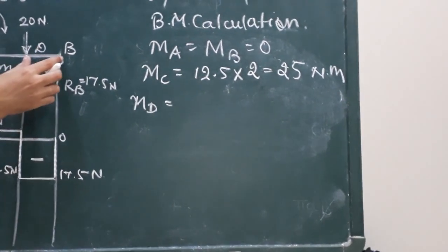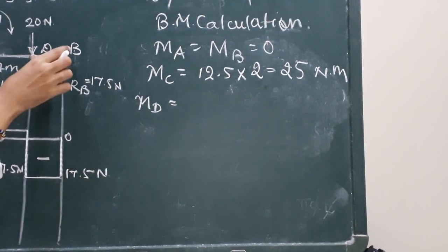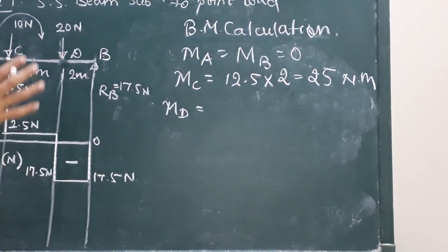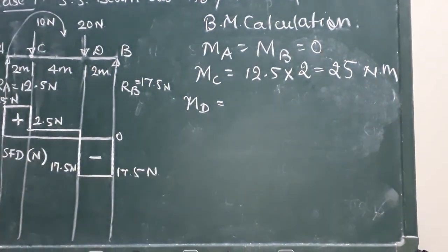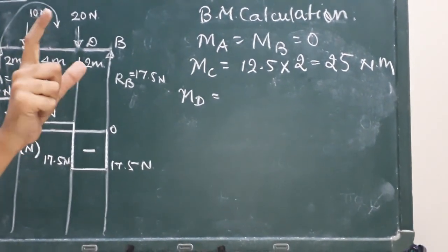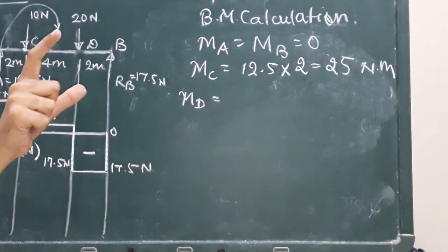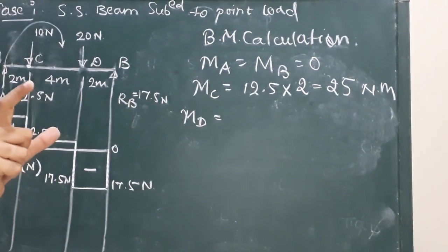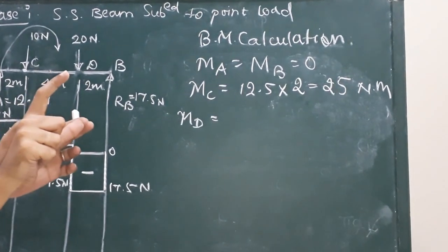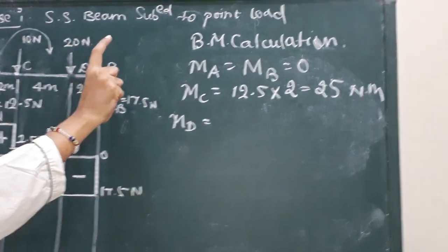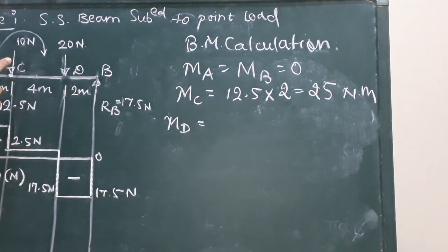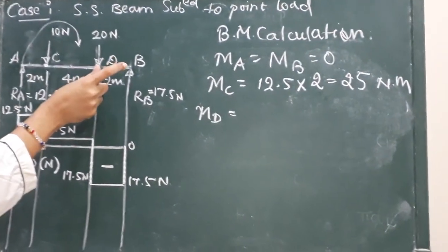On the right, this force is going anti-clockwise. Now how to see whether the force is clockwise or anti-clockwise? So what you have to do, you have to assume these two fingers, the thumb and the first finger, as a rounder. Right? And assume that this one is the tip of the rounder and this one is the pencil. Put the tip on the point from which you are finding the moment, right? Either from B or D or C or A. Suppose I am finding from D, right?